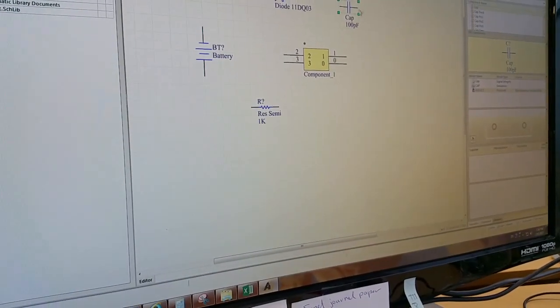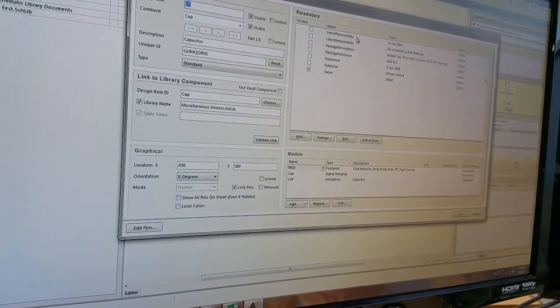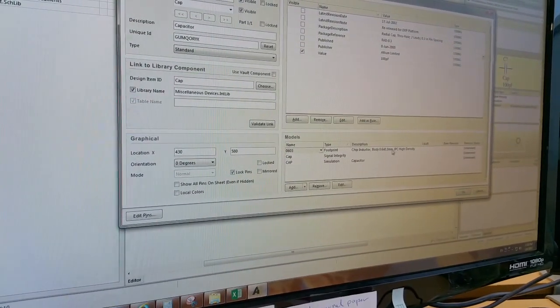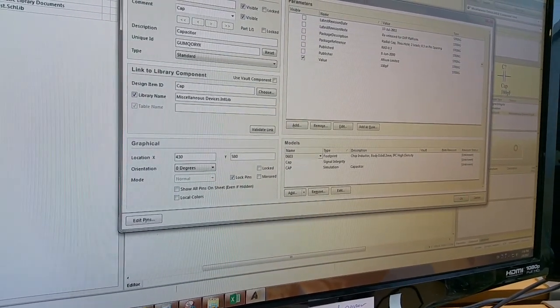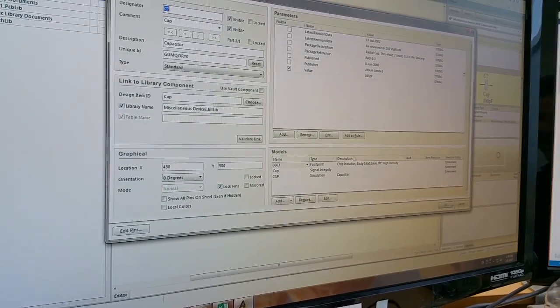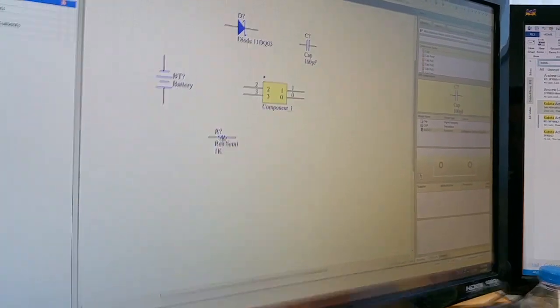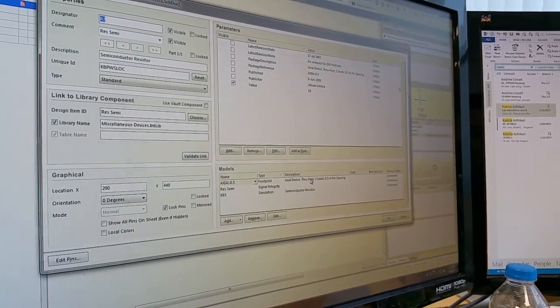Okay. So we change the capacitor. This capacitor is not changed in the footprint, you see, change it. We don't need that one because this is the library. We don't care about the library, but we change that one now. If you want to change that one as well, double click. You see, resistor, through hole now. You don't need through hole.